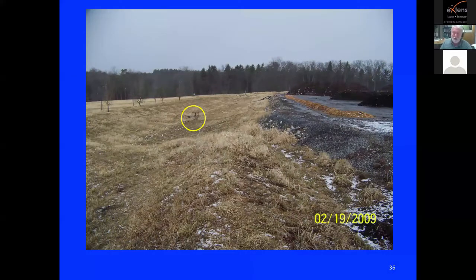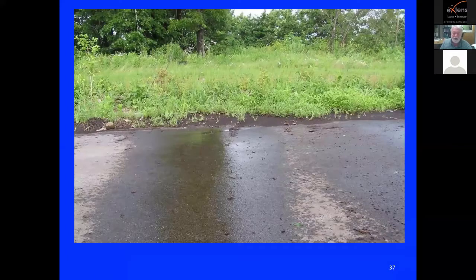One thing you might want to take a look at here, on this same area in a different season, fines are collected right where the pavement ends and the vegetation starts. So this vegetation area and the change in slope and the change in roughness all make the fines settle out right here at the start of the best management practice, which in this case is a filter strip.